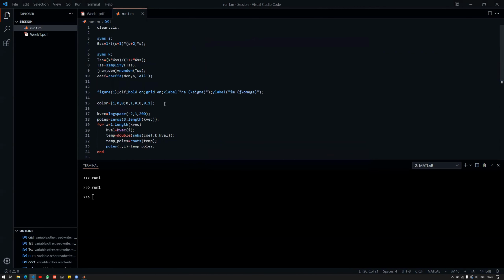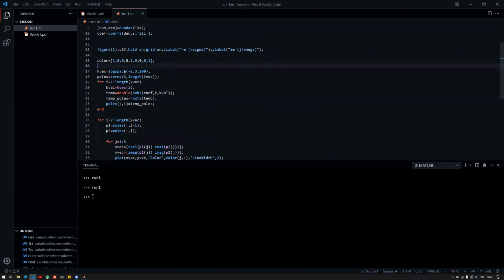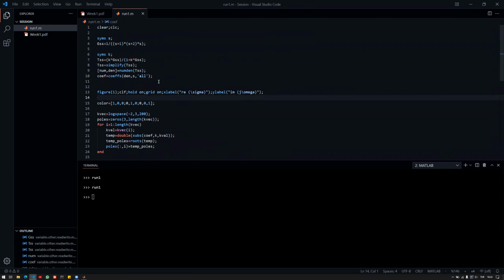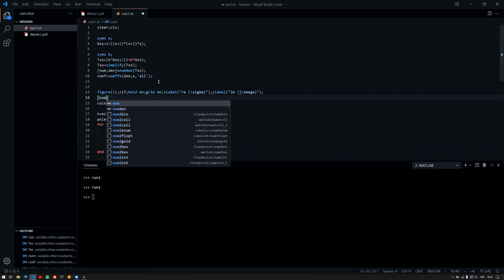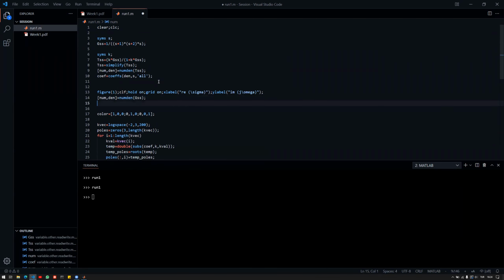And we can solve that by, well, if you're lazy, you might go ahead and, since we have 0, oh, we don't have 0, by the way. We have 0.01 in our k-vec. So what you can do is you can go ahead here and use, again, num-den, numerator and denominator, to extract the values out of the open loop. Now, then we will have the denominator. Let me copy and paste this code here. So here, now what we can do is we can get the coefficients.